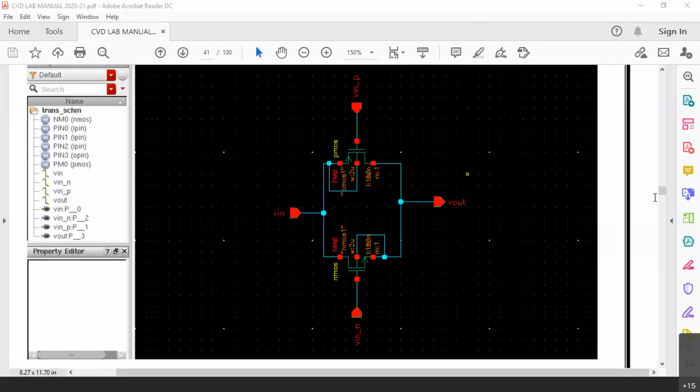That means whatever circuit you have been studying till now is static Cmos. But the direct logic of AND and OR is possible using a transmission gate. So Kuldeep has given the answer. It is easy to implement a latch and flip-flop. I cannot completely endorse this answer, because using static Cmos also we can implement a latch and flip-flop, not just using a transmission gate. And Kuldeep has also given the answer, we can implement AND logic gate. Correct. AND gate and OR gate can be implemented directly using a transmission gate.